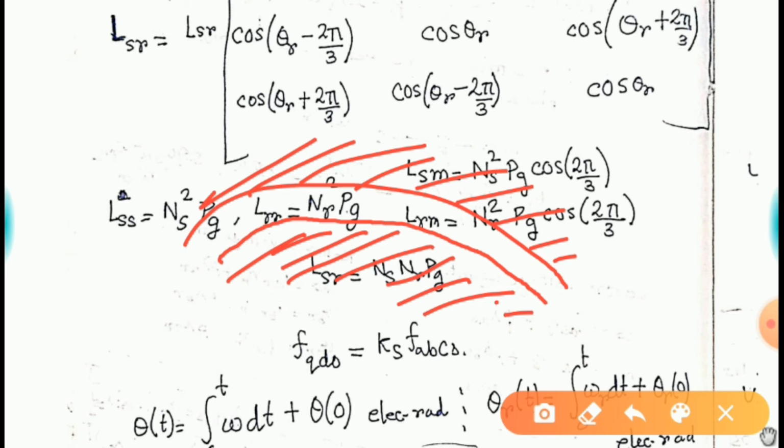So irrespective of the geometry of the air gap, your permeance depends on your material and the distance between them, right? So here that perpendicular distance always remains constant. So in this total thing we can expect a constant permeance along this path.